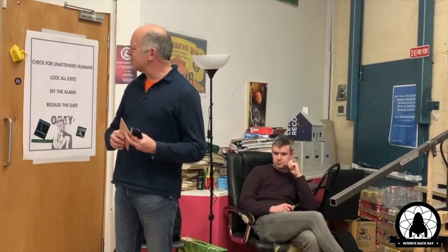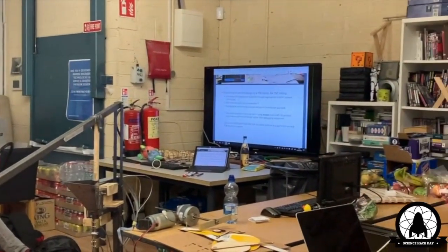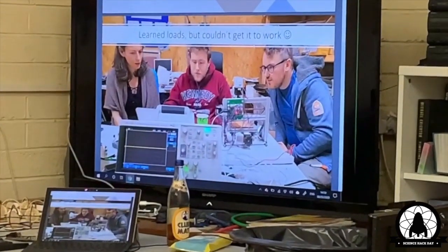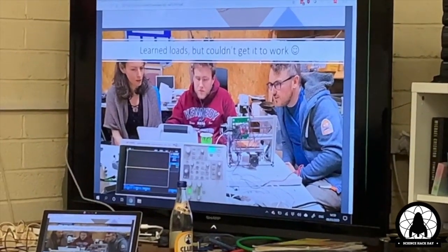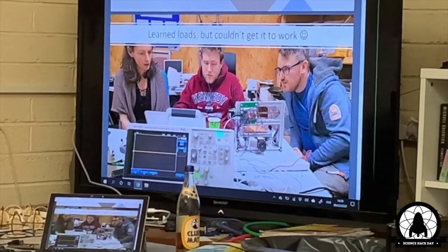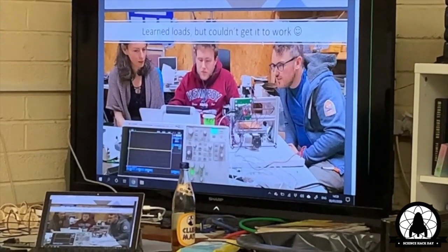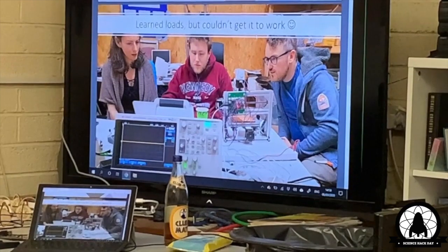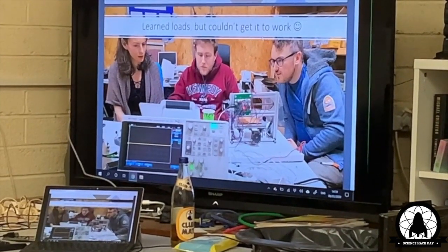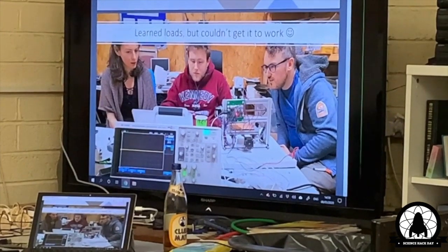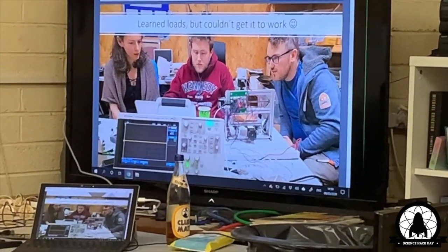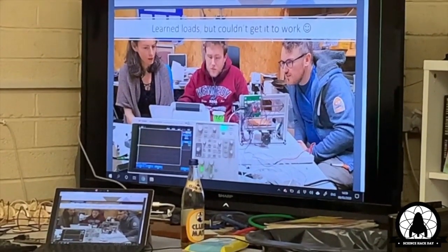And then we went to the next thing of using this little machine down there in the corner to cut out our printed circuit board. Loads of people have one of these machines on the web. Everybody's done it before. But actually, there's a million configuration options required to set the machine up with your data file before it will successfully print, which we were unaware of when we started.